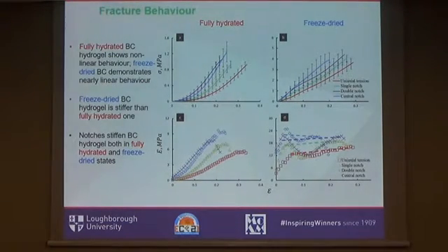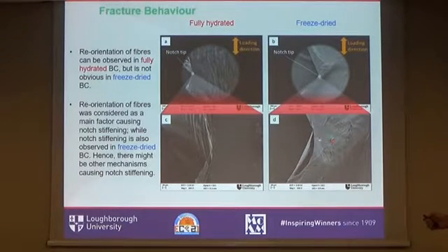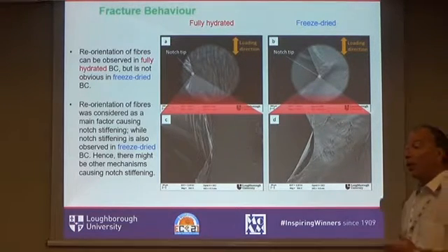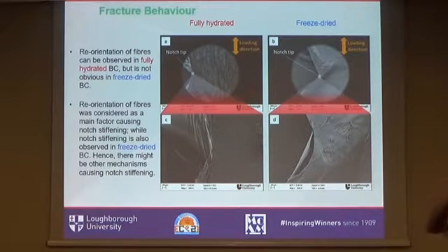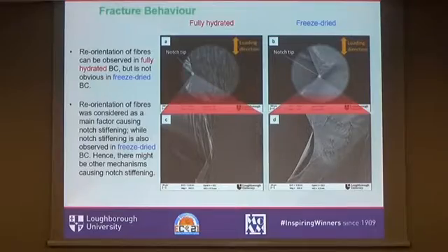The reason for this, and we observe this in other non-woven materials, is that the crack which you have introduced in the system, in a continuum, will result in different types of singularity. Pretty straightforward in the elastic case, a little bit trickier in the elastoplastic or viscoelastoplastic case. Here, even at this resolution of several microns, you can't resolve single fibers. The crack effectively crosses through the nanofibers, but the fibers at the very notch are not affected by this. So there is obviously a local distribution, but in reality they have the possibility to avoid crack propagation by reorienting and transferring the load to their neighbors, and as a result we have a stiffer situation.